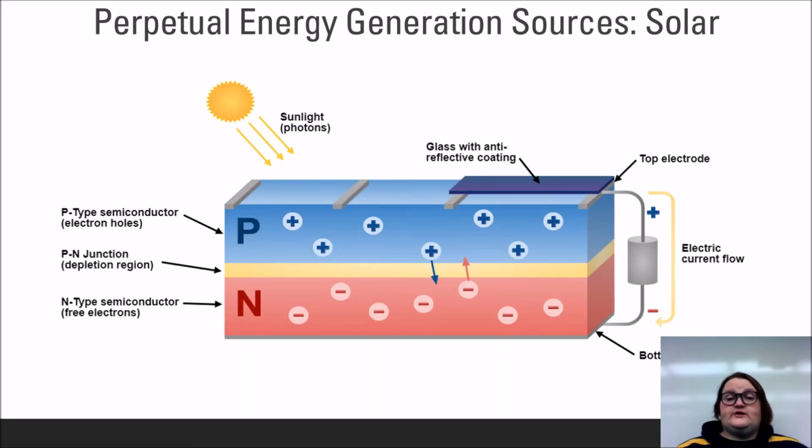The use of solar energy to produce electricity is done exclusively through the use of PV panels. PV panels are essentially two semiconductors with a junction between them. Each semiconductor is connected to an electrode with a particular electric charge. These semiconductors are beneath a layer of glass with anti-reflective coating, which is designed to ensure that as many of the photons as possible are engaged during the process.